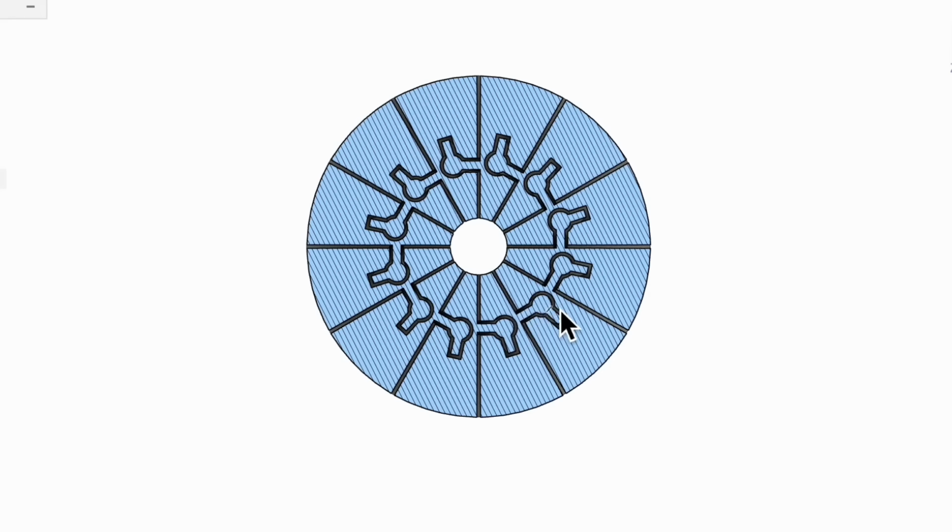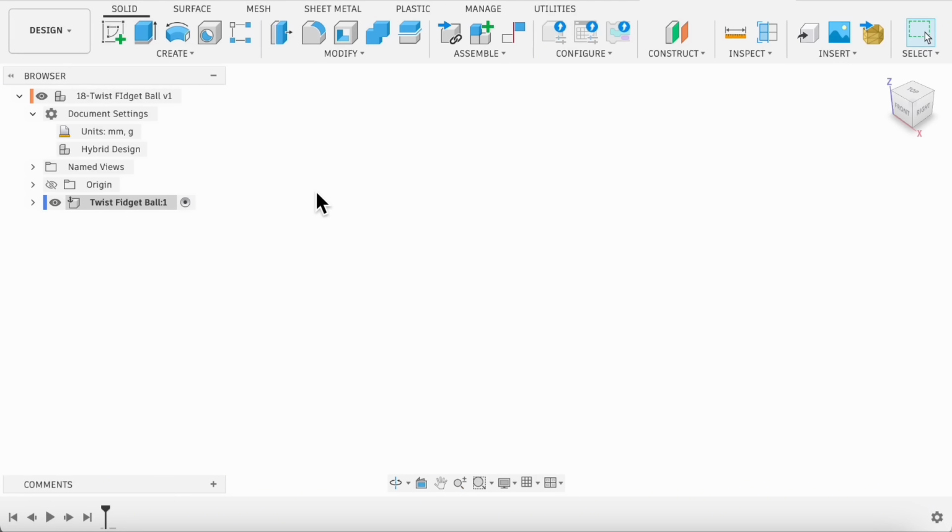To keep the segments from sliding apart completely, there's also a small rectangular stop feature built into the side of the slide, the captive pin slot. The pin travels inside a closed-ended slot on the neighboring segment. It can slide freely up and down, but once it reaches either end, it's blocked by the wall of the slot. This keeps all the segments securely connected while still allowing smooth movement. All right, hopefully the mechanism makes a bit more sense now. Let's get back to the modeling.